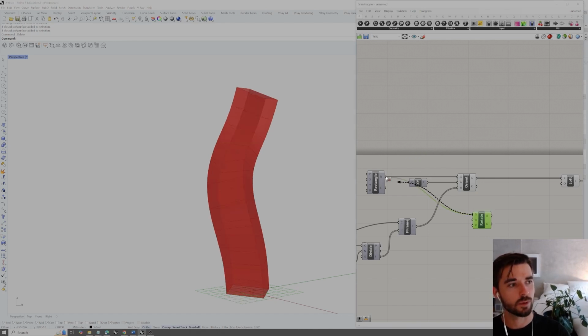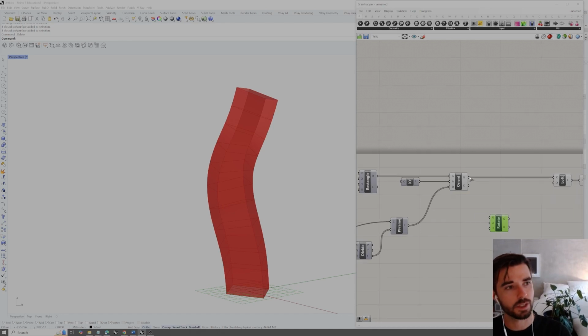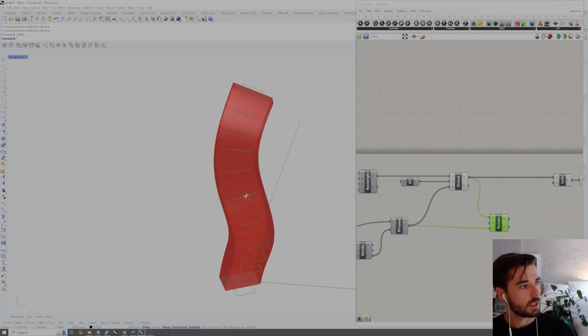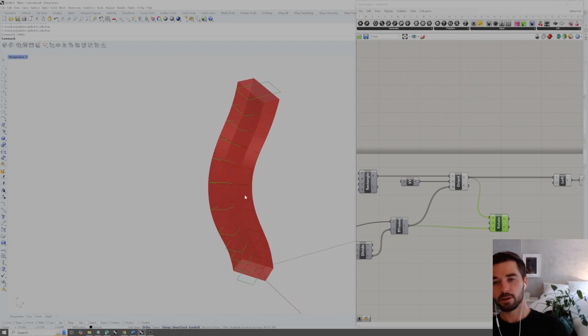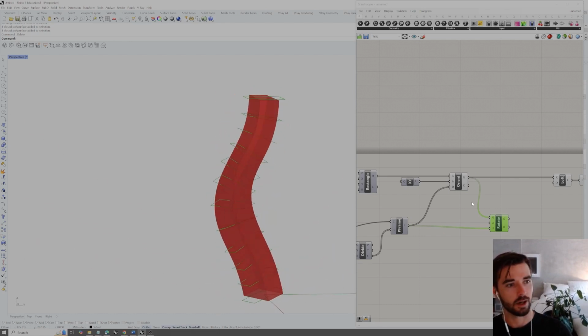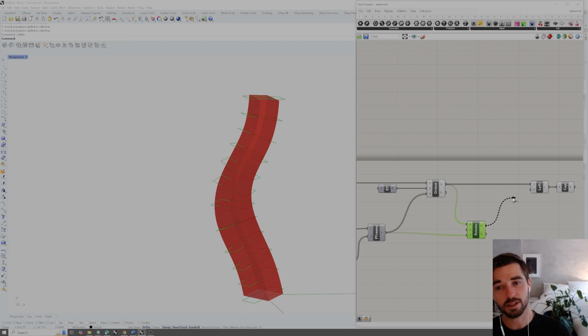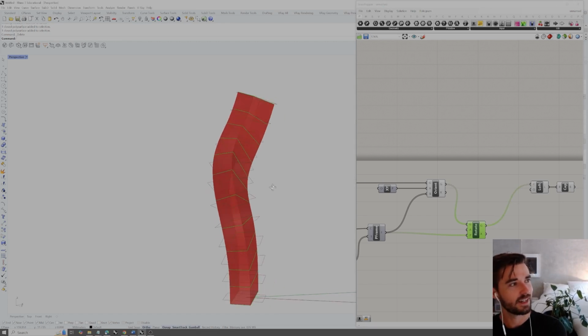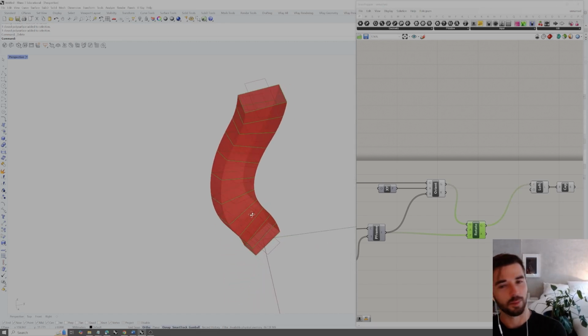We want to be able to rotate every single one of these oriented sections, so get that level of control. In order to do this, we need to plug in all of the oriented geometries into rotate, and then instead of using the XY plane, we actually want to use the perpendicular frames themselves. So this gives us every single plane, or every single section, rotated 90 degrees around the plane that it's on itself. And now if we plug this in, it's basically going to do the exact same thing that we just had, so not terribly exciting, as just rotating them all by 90 degrees.